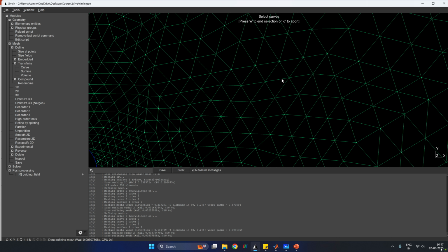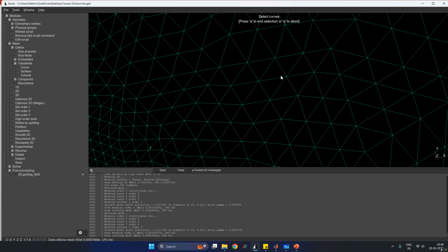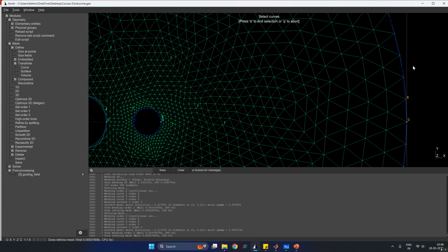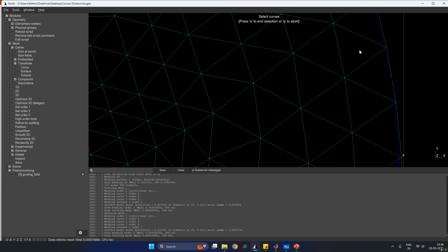If I was writing the row for this node in the stiffness matrix, I would get the contribution from all of these 6 elements. But for the boundary case, if I was considering this node, I would just get contributions from three of these elements, so only from one side. So this doesn't represent a perfect flux balance, rather this is more like an insulation.